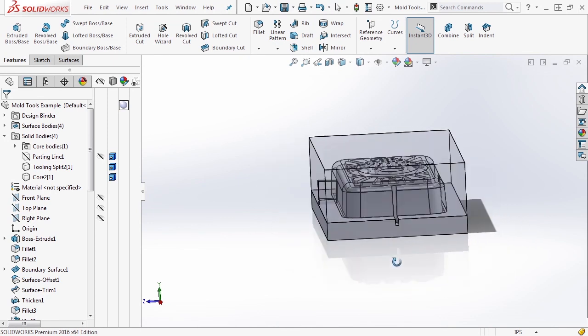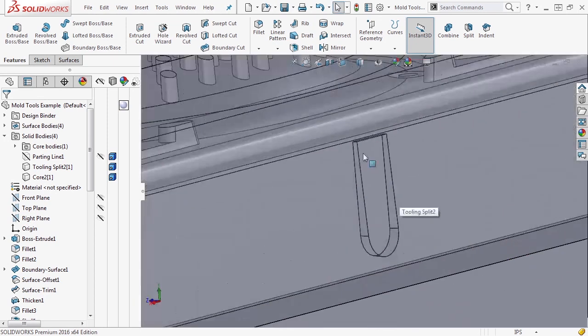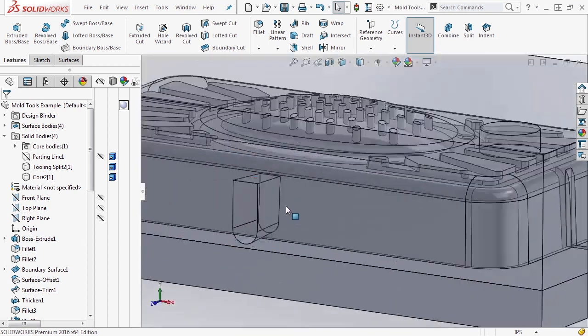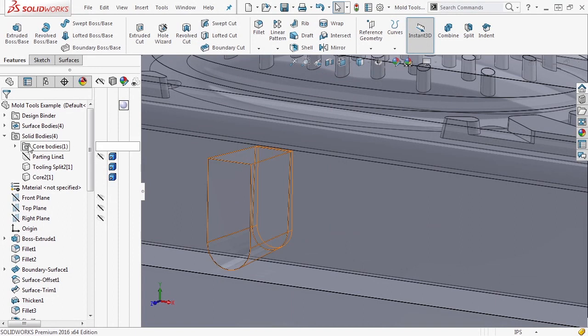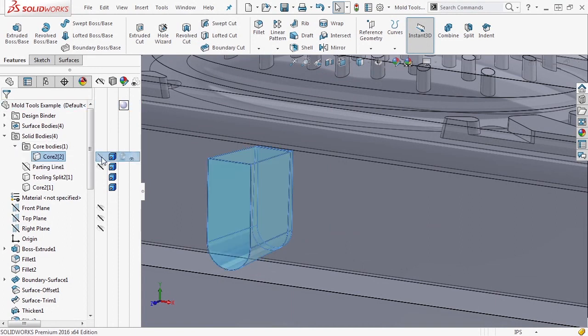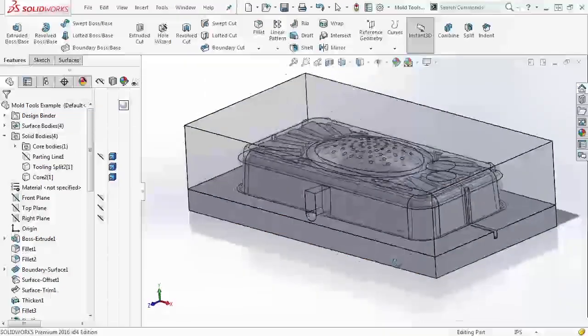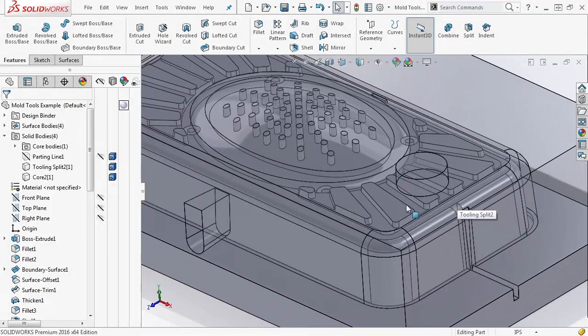So you can see here in the mold, as we rotate it around, that area that was an underhang or an undercut is an area where this thing maybe needs to snap into another part. And we can use what's called a core body. And you can see this core body here is a separate piece that gets pulled out before the rest of the mold is disassembled.